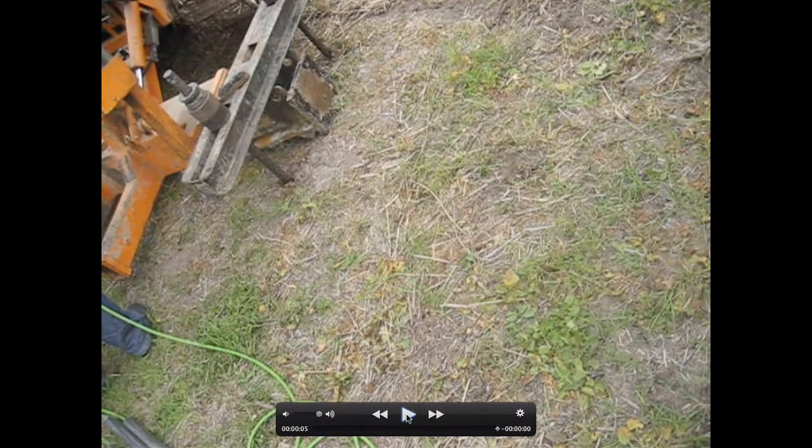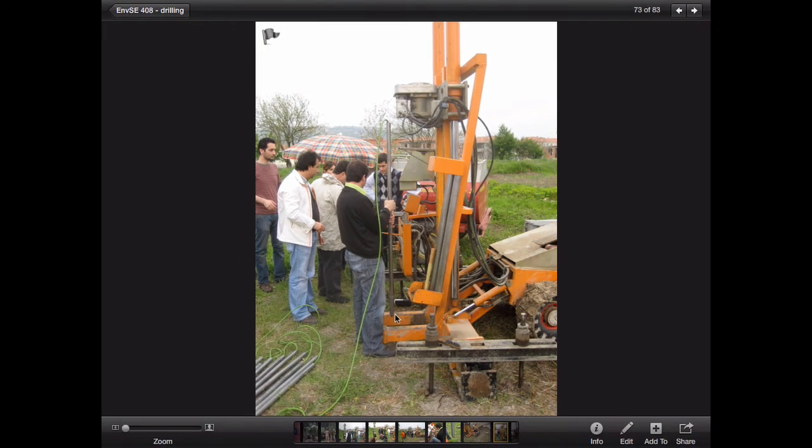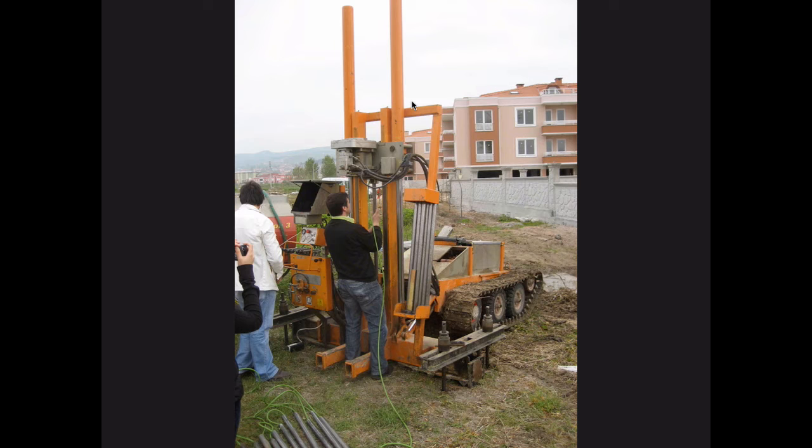This is me taking pictures of my feet. But here you see it. So this is the deal. This is the tip. It's ready to be put into the rig. These are pieces of the drill steel here, but it's easier just to keep it on the ground. It's had the stuff threaded through there. It's ready to go. It's physically put onto the ground, and then this mandrel clamps onto it and just slowly forces it down.